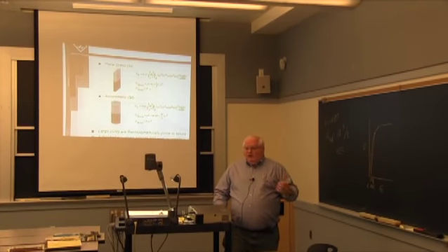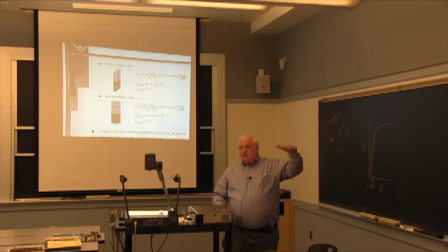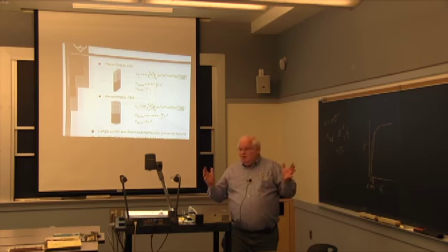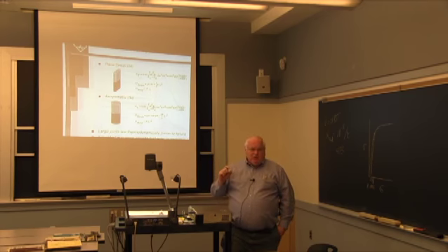And most people don't realize, even in soldering, except in soldering, you have this material that's going to creep. And so you don't get a lot of residual stresses because even at room temperature, the solder creeps. But if you're doing brazing or diffusion bonding, and you're up at 1,000 degrees centigrade for your bonding temperature, this thing's going to go through yielding on its cooling for a dissimilar metal joint. And it's just the way it is. Most people haven't stopped to think how little the delta T has to be.